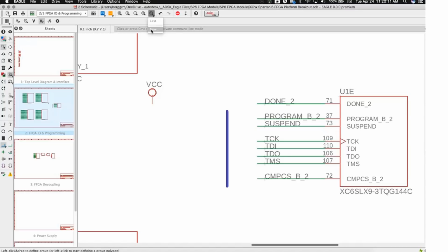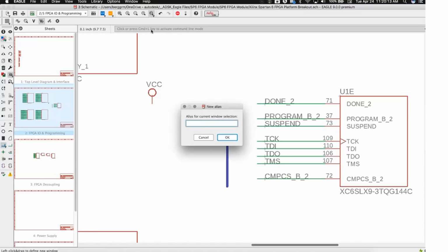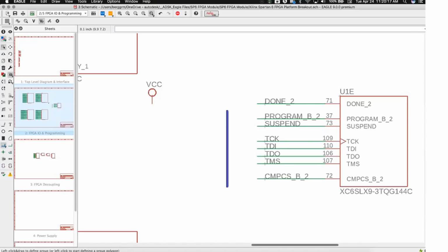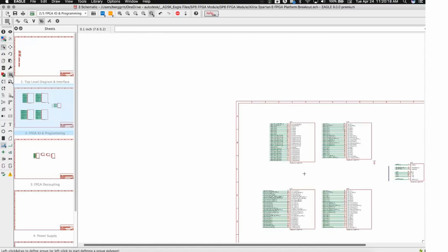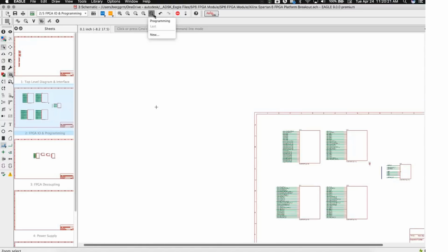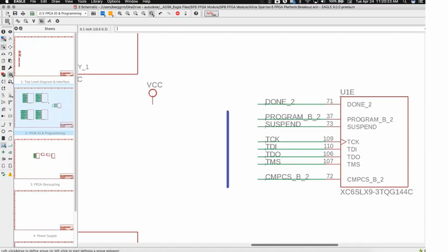In the layers command, you can create aliases to quickly switch between views. That's where I use it the most, for the layers. I have every combination you can imagine, like for Gerber outputs. That way I could preview it as well. Absolutely. Right. Same for the add command.